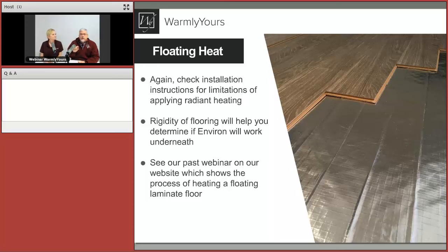So you don't want to use like a 1/4-inch carpet because it lets it bounce too much, and you don't want that. And what you always want to make sure of is that this particular aluminum mat needs to have a soft side somewhere. Mm-hmm. So if you put it against a hard wood that's over it, you want to make sure that there's a pad between the environment product and the subfloor. So there's some give to it. So you never put this between two hard surfaces.